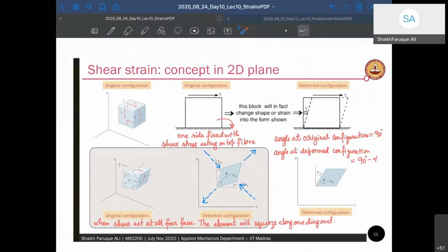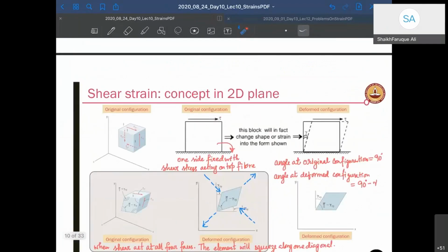Now in this picture we had only one angle change. In this picture there will be two angle changes, right? Since the material body is a perfectly symmetric body with symmetric loading, a very small element, there is no discontinuity between them. We'll assume that both of them are of the same value, gamma xy by 2 and gamma xy by 2. That's an assumption. It may not be true if the material is not homogeneous or not uniform at that point location.